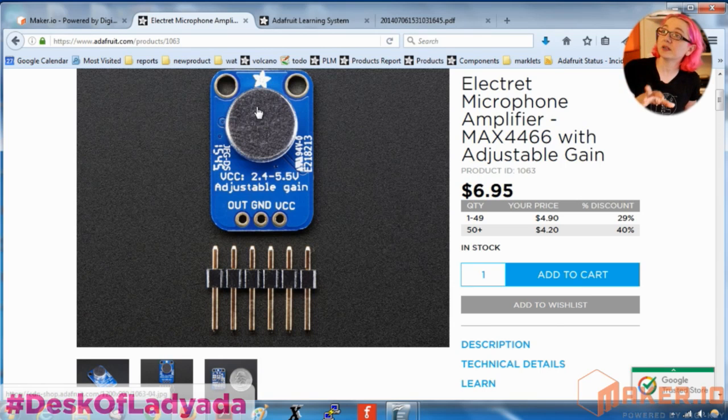So anything you can get surface mount is preferable, if it's the same price as the through-hole version. So if we can get a surface mount Electret mic, Electret mics actually can't be reflowed either; it has to be done after the fact. But if we can get a microphone that can be put on a feeder, then it's a lot less expensive. Do you want to show off what a feeder is?